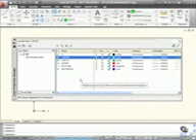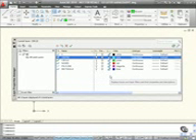So as you can see there, there's lots of ways of actually changing your layer settings, not just creating new layers, giving them line types, colors, and names. Obviously, you've got the standard tools there, things like on and off, freeze and thaw, lock and unlock. But as you can see, you can adjust those settings and manage your layers a lot more effectively by utilizing the tools there that allow you to change your layer settings within the Layer Properties Manager.